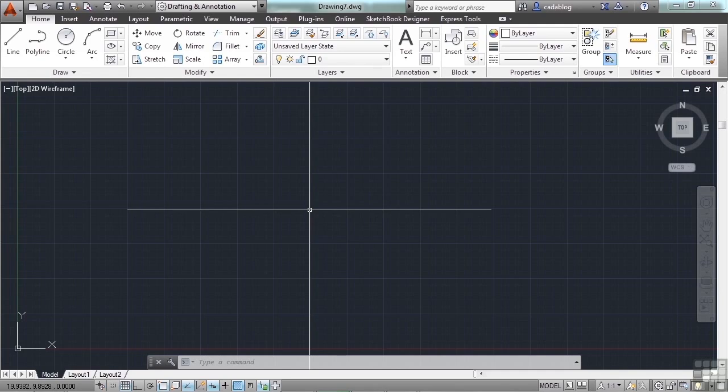This is good for several reasons. 1, you are always creating an accurate drawing. And 2, your drawing will be properly drawn to scale when printing. And 3, others that need to use your file will know what's going on with your line work. Typically, AutoCAD users will work with one set of drawing units, whatever they might be. Sometimes, though, you will need to work with files that are drawn in different units. That's why it's so important to define your units in the Unit Manager.